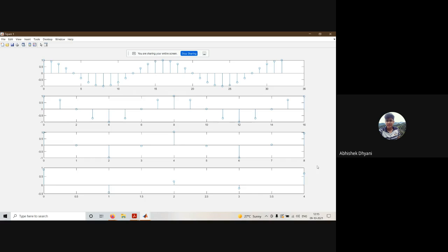And that is because for d is equal to 8, there has been aliasing. If you look at the frequency domain, you will see that there will be aliasing, because now the frequency spectrum is not between minus pi to pi. And that is why in the last case, when we have used d is equal to 8, the signal cannot be recognized. We cannot say that this is a cosine function.